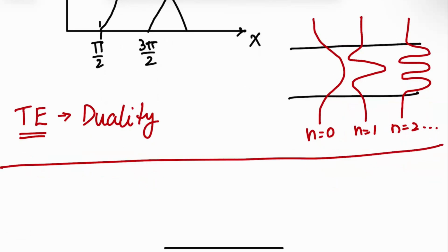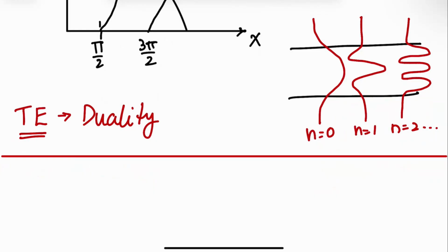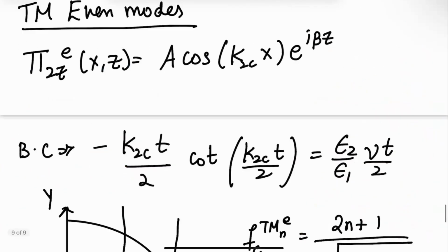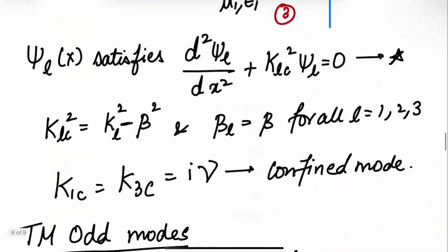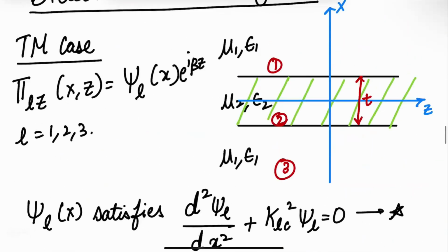So this is an interesting and important problem because heterojunctions in semiconductor optics use these kinds of slab waveguides. So solving for what kind of modes can propagate in them is very valid. Another important case, which we'll look at next time, is if I set the lower medium to be PEC, then this just looks like a dielectric coating on top of a PEC, which is very broadly used. In silicon chips, the silicon substrate is usually laid on top of some kind of dielectric, or even if it's in air, then you can have substrate modes that propagate in that silicon chip or in that substrate, and those are called substrate modes.